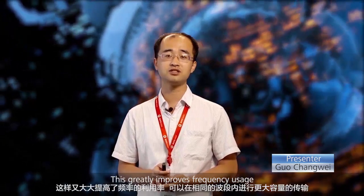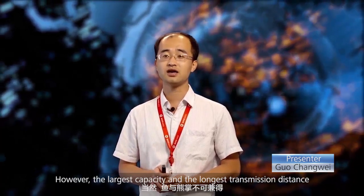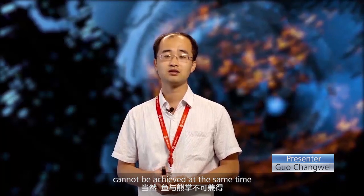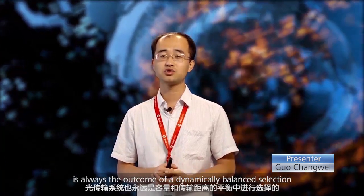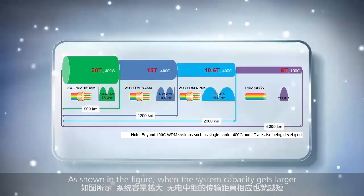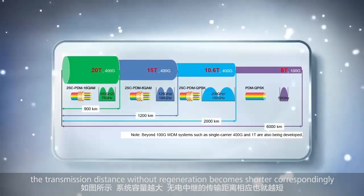This greatly improves frequency usage and can transmit larger capacities within the same band. However, the largest capacity and the longest transmission distance cannot be achieved at the same time. The capacity and transmission distance of an optical transmission system is always the outcome of a dynamically balanced selection. As shown in the figure, when the system capacity gets larger, the transmission distance without regeneration becomes shorter correspondingly.